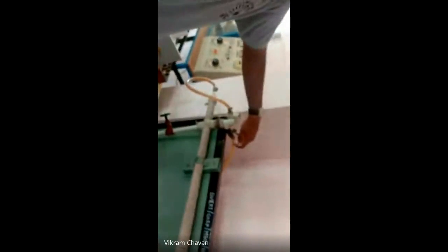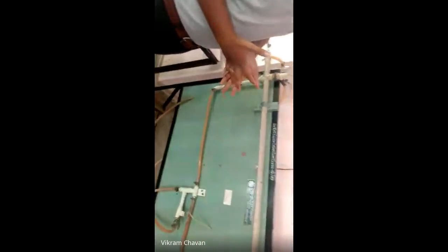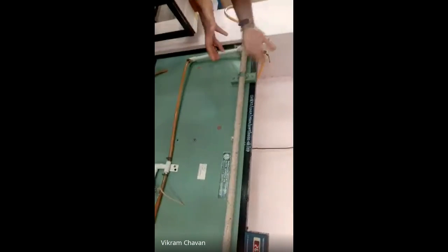Cold water will flow in this direction, it will enter over here, it will come over here, and then we will open this particular knob. So in that case, what will happen? The hot water direction we are not changing. The hot water direction is in this direction only, and the cold water flow will be in the opposite side. So that will be our counterflow arrangement. And in that case, we have to consider the readings.